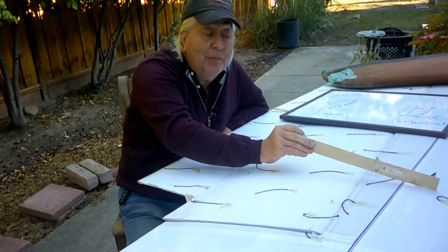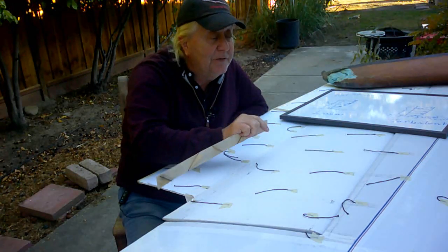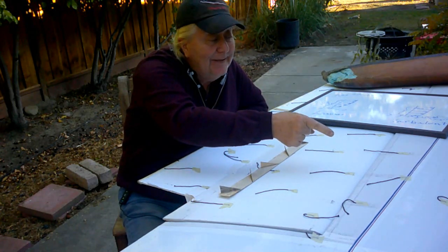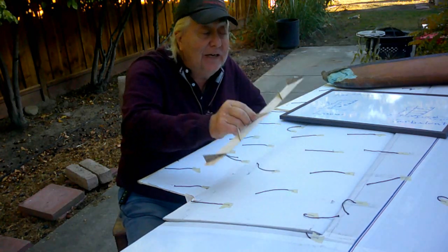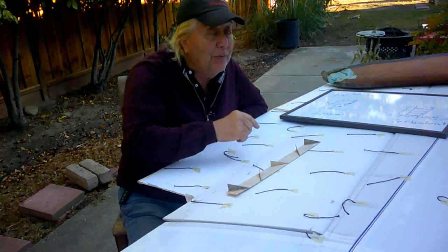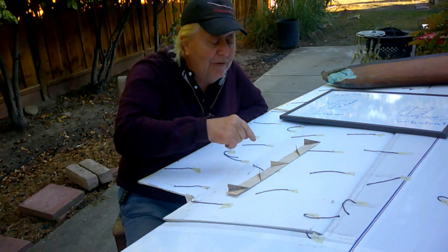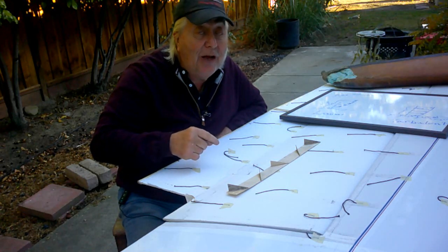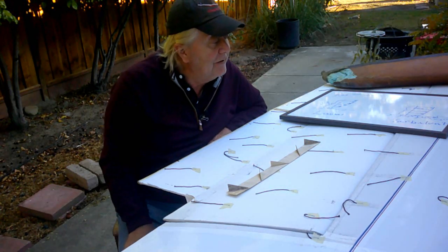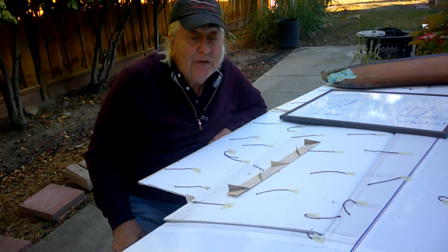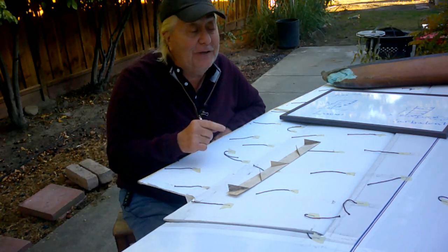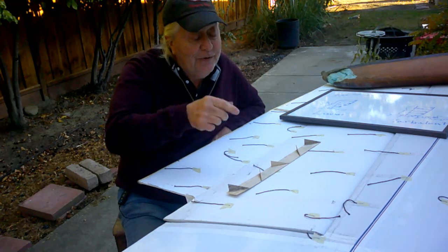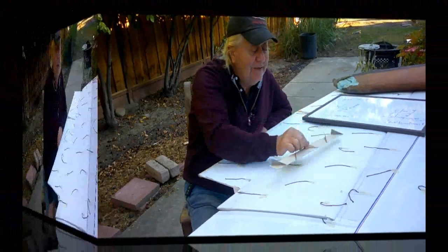And the way these structures are built, right to the nub in terms of strength to weight ratio, if I cut a bunch of slots in that D-tube to allow these guys to pop up, I'm going to have to do a bunch of reinforcements. I have to carry the loads around those slots, and it's going to get heavy and complicated in a hurry. Plus, in order to make that modification, I have to build two new wingtips. Well, gosh, it's a good thing I hadn't finished the other wingtips, because I might need to get inside the D-tubes and cut slots and reinforce and build something like this into the D-tube.